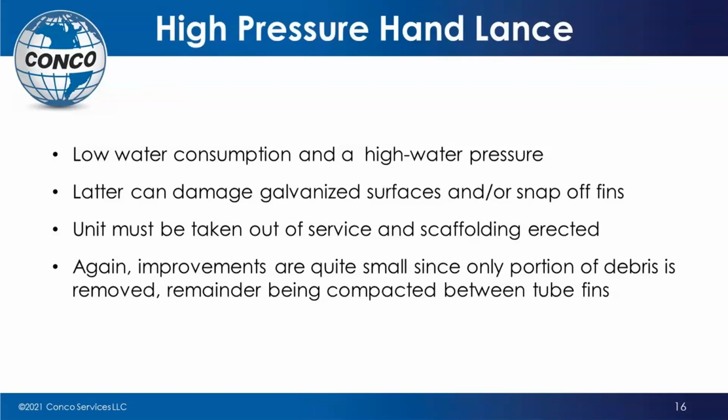In fact, once that angle changes to a certain portion, you then begin to impact the fins themselves, and that angle can bend the fins, or you can take the galvanized coating off the fins themselves, so you can damage that surface. So you've got to be very careful when using a high pressure hand lance. Again, you've got to put up scaffolding. That raises the safety issue again. And in the end, because it's manual and somebody's got to do this, you're going to have small improvements because you're only going to get a portion of the debris out, and you're going to end up with damaged fins in the long run.